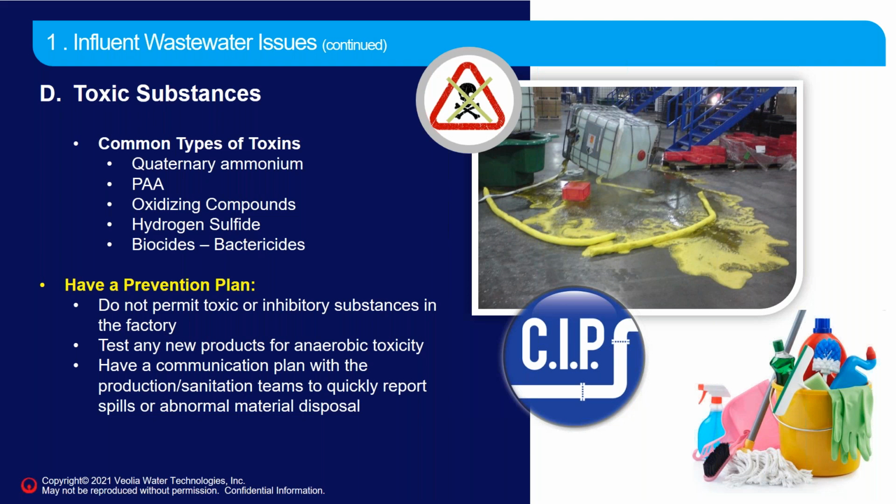You have to change that around so that people know that they'll get in trouble for not telling when these things happen. Oftentimes, if something happens in the production facility, there's a spill, if you call the wastewater treatment plant, they can make plans, divert, do something that would help to prevent those potentially toxic compounds from killing the biomass.